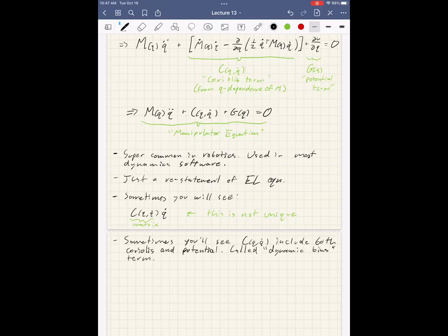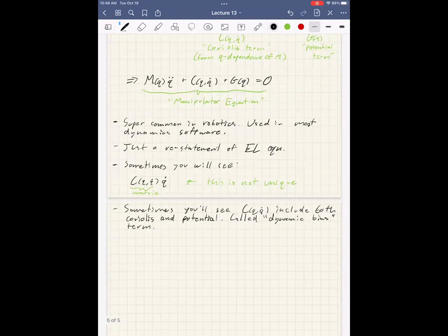That's the standard thing in a lot of packages that implement Featherstone's algorithm, like recursive Newton-Euler, things like that. We'll do it that way and call it that. So yeah, there's some fuzziness in exactly how you define this thing. You'll see subtle variations, especially in the Coriolis term, being written a few different ways. Let's see. Any questions about that? Okay, everyone's pretty much seen that before.